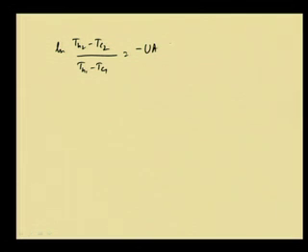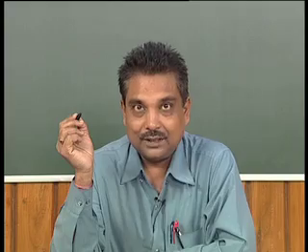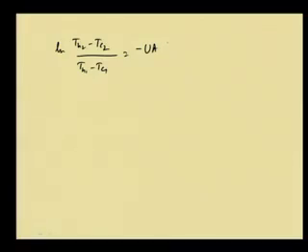We will assume certain aspects here: in the heat exchanger the specific heat capacities are not changing with time, and the overall heat transfer coefficients are not changing with time. These are the inherent assumptions that we have taken while doing this derivation.